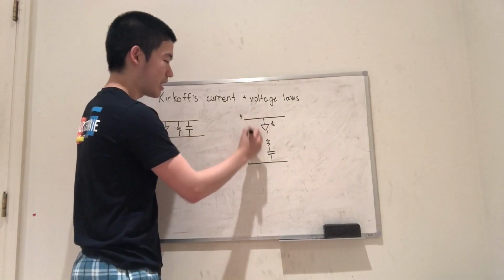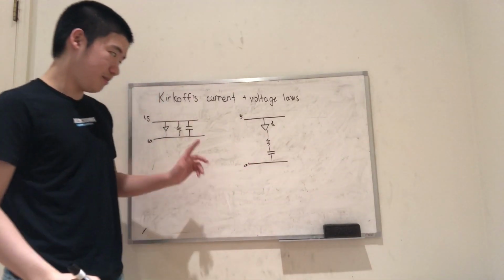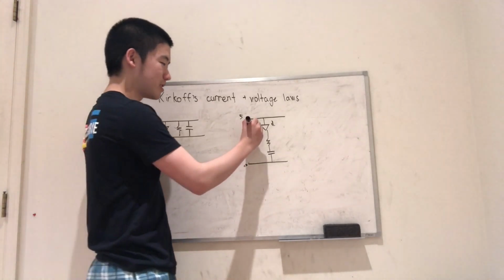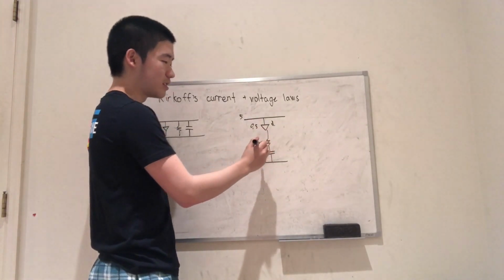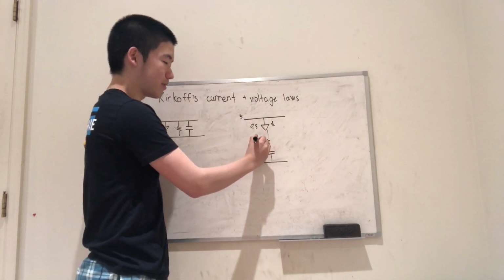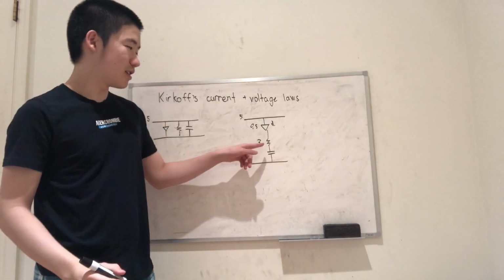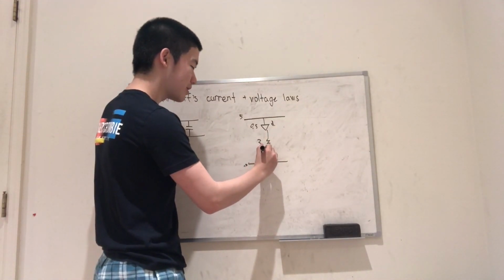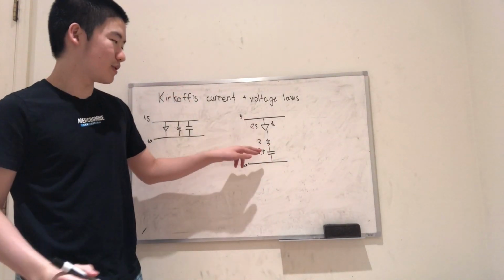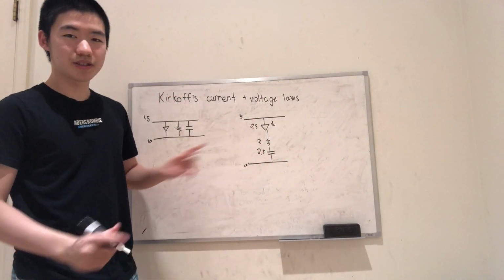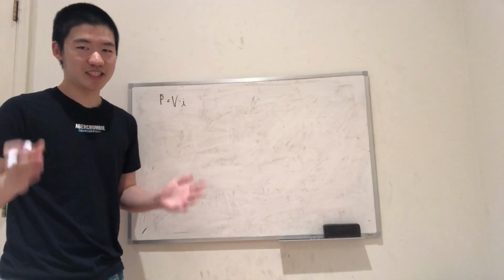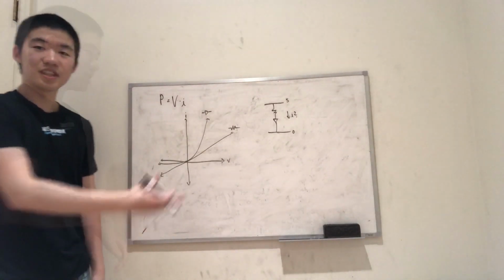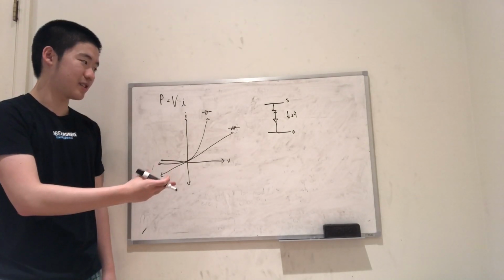Additionally, say you had 5 and 0 here again, then we know that across this diode, if we have 0.5 volts, and if we have 2 volts across this resistor, then we know that across the capacitor we must have 2.5 volts, because all of these voltages should add to 5 volts. Now, how exactly is that going to help us determine how to minimize P? Well, let's take a look at this example that I've set up.